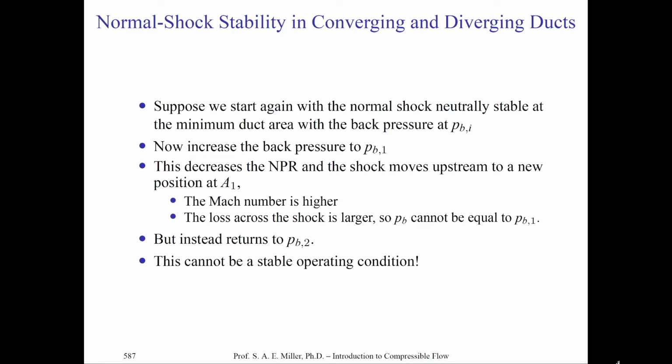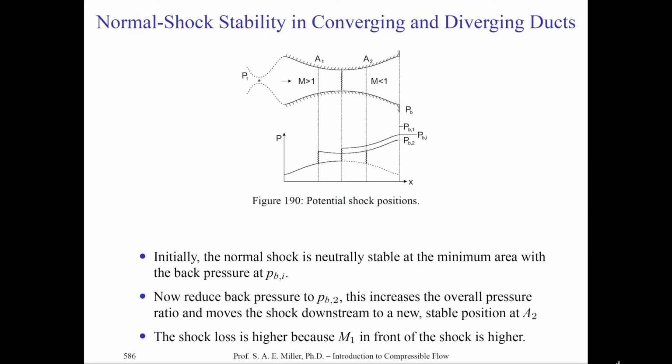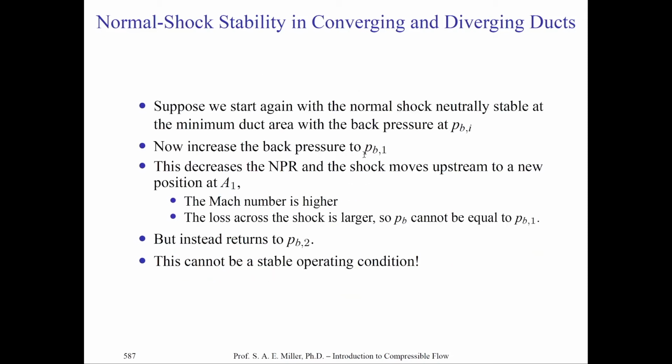So we can start to see an idea of how we should operate our tunnels because we want to have minimal losses. In fact, you would try and adjust the back pressure and area ratio of your second nozzle so it swallows the shock, and then adjust back pressure and areas so that, by lowering them, you put your shock wave closer to the throat for lower losses.